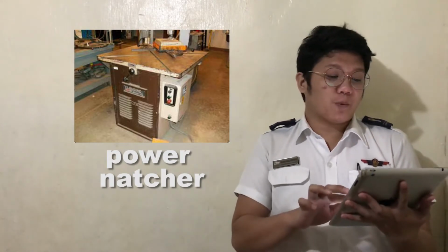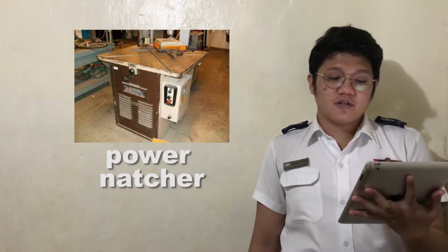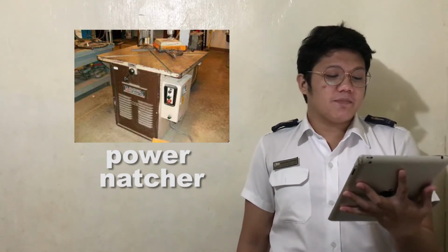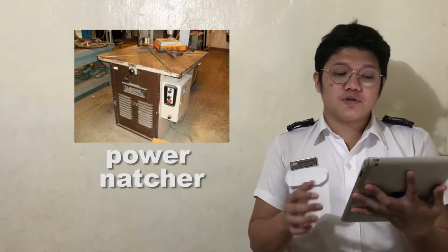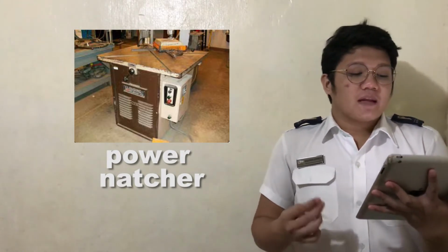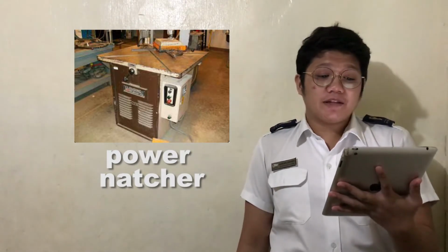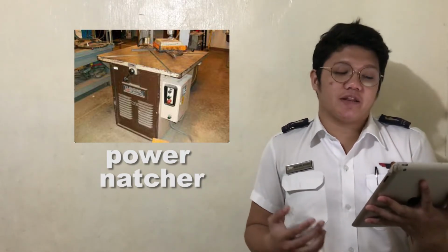Another one is a wet or dry grinder. Dry and wet grinders are found in the airframe repair shop. Grinders can be bench or pedestal mounted. A dry grinder usually has a grinder wheel on each end of a shaft that runs through an electrical motor or is pulley operated by a belt. The wet grinder has a pump to supply a flow of water on a single grinding wheel.